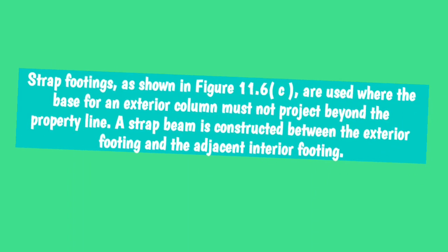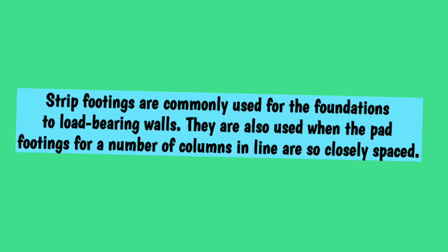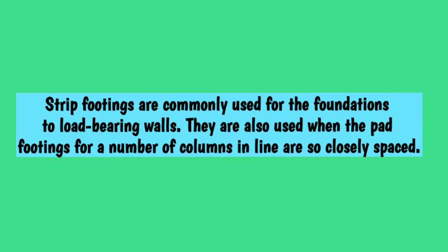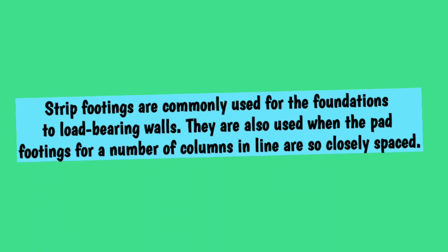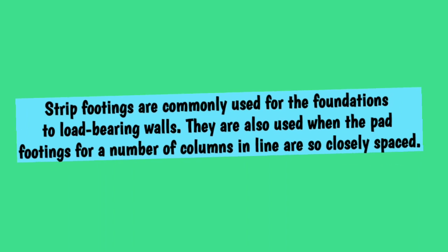Number four, strip footing. Strip footings are commonly used for the foundations to load-bearing wall. They are also used when the pad footings for a number of columns are in line or so closely spaced.